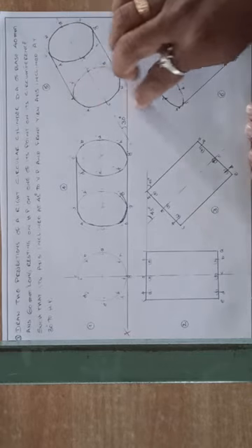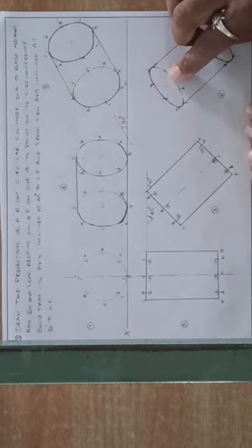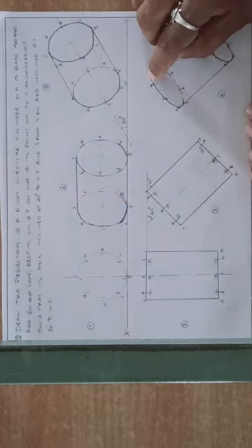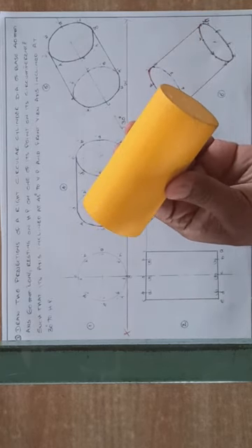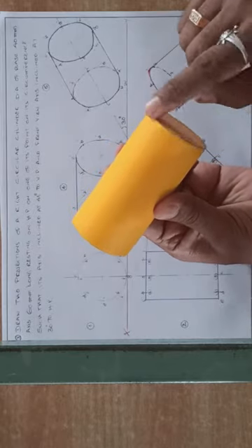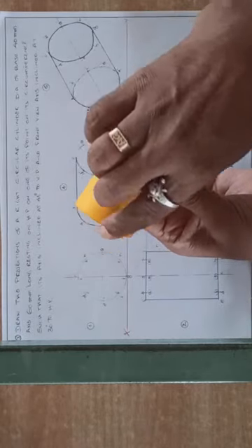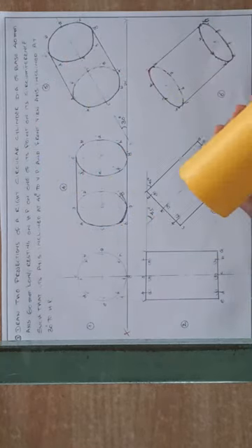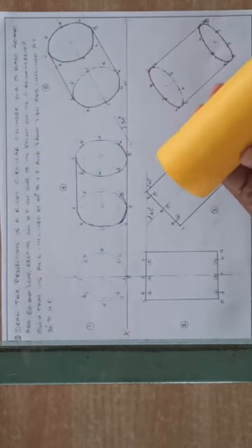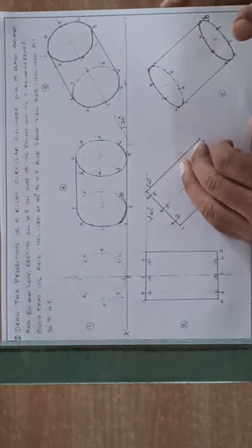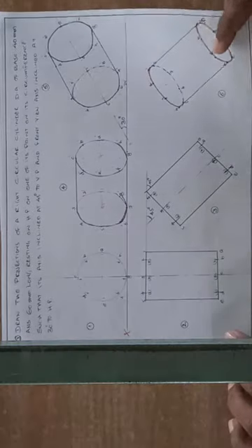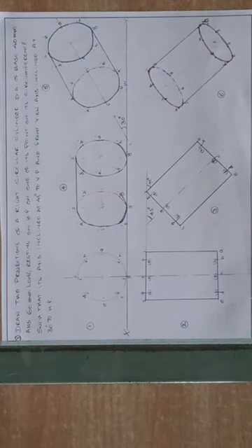Same procedure, again project the points from the base, second face. Here also horizontal projections. Here also carefully mark the points. First half is visible, second half is not visible, like this. So now the object is like this. You can see this face, so this face is visible. Here half visible, half not visible, it is also there, right? From the top view. So like that you have to practice the problems. So that is prism and cylinder. Now coming to another